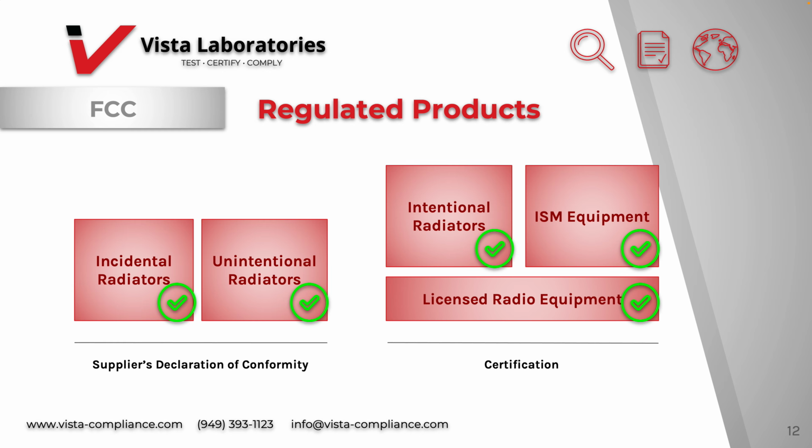Intentional radiators and unintentional radiators fall under SDOC, which also requires testing, but it is the responsibility of the manufacturer to warrant that each unit of the equipment complies with the FCC rules and does not require TCB review.